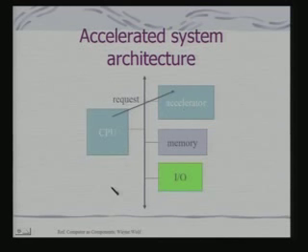The accelerator performs the function; to do so, it accesses the data in the memory, and can write the result back to the CPU or the memory, or it can write the data onto the memory and inform the CPU that it has written the data onto the memory. This is how typically an accelerator functions, and this interface forms part of your glue logic.